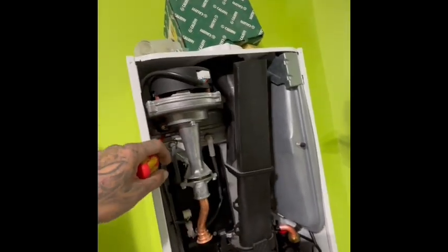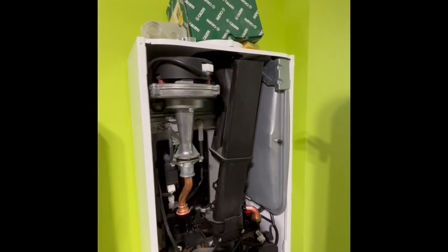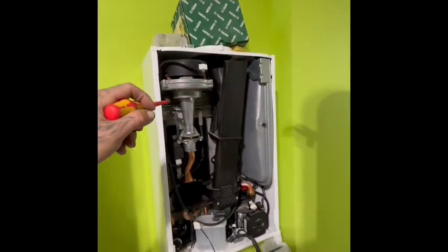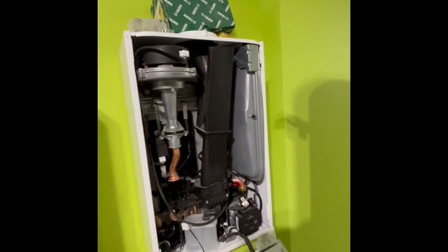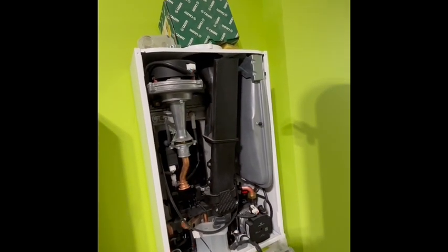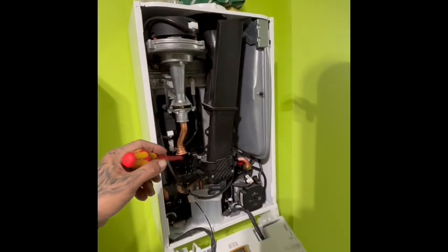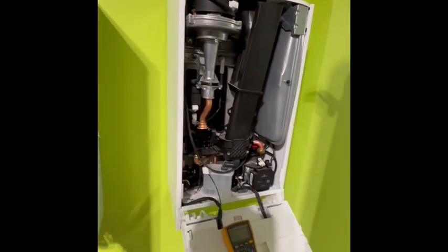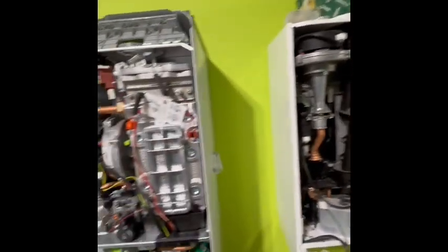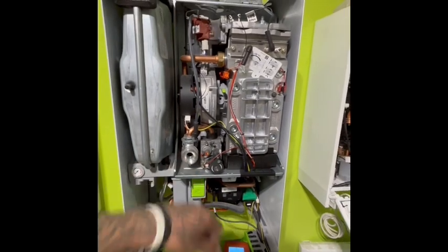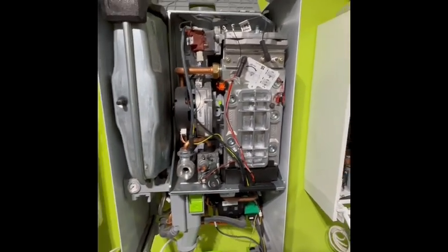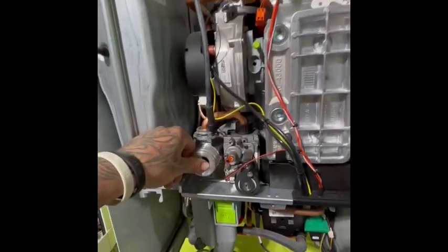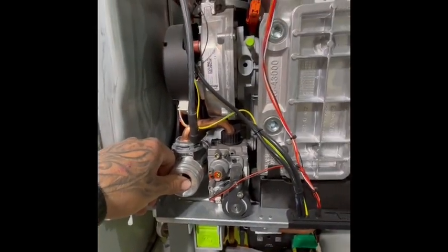They have spot welds that come away inside and they cause a vibration noise. Most people say that's down to the spot weld. I generally find that vibration noise from the burner is down to a blocked burner itself, not the spot weld itself. You'll also get the gas valve on this particular boiler causing the exact same fault. So it's easy to work out sometimes if you've got enough gas going into it, or it's an airflow problem. When it's going through ignition, if it won't light, you can simply restrict the airflow a little bit, see if that will light.